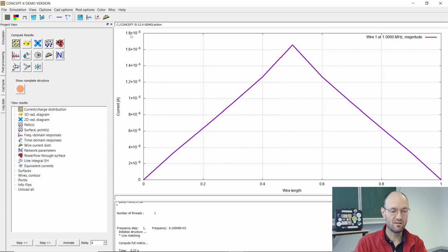It's something also in the microampere range. And even if we have now 1 volt of excitation and not our 8.77 millivolts, the amplitude here does not really work, unfortunately, because we don't have this top load, and the current distribution does not fit the assumption of the constant current.